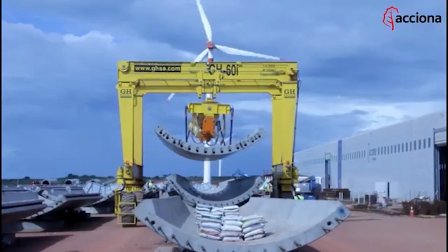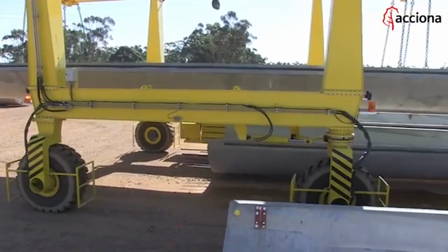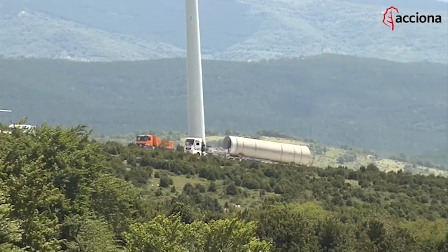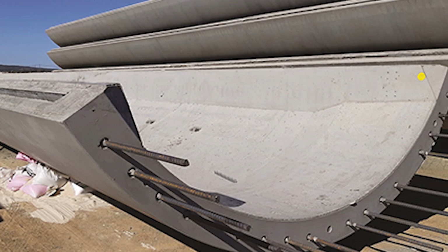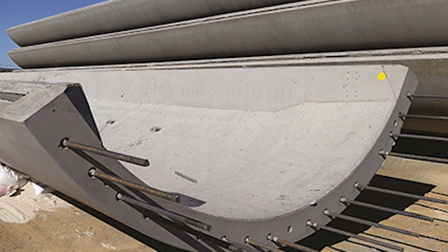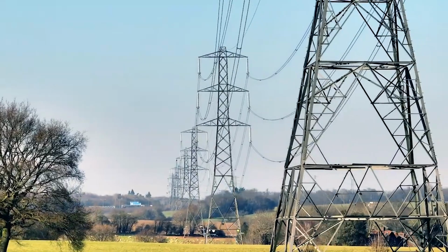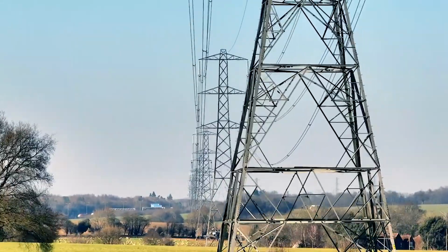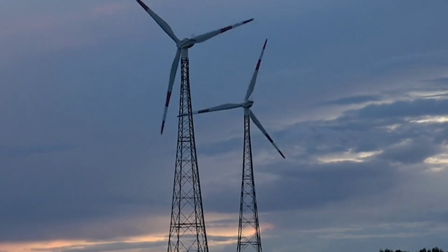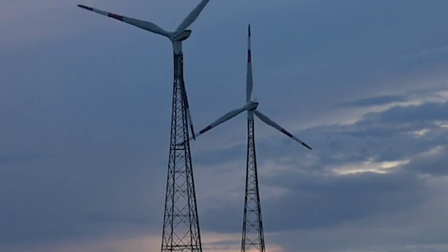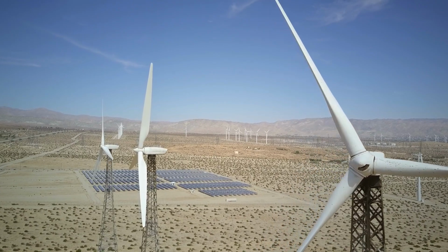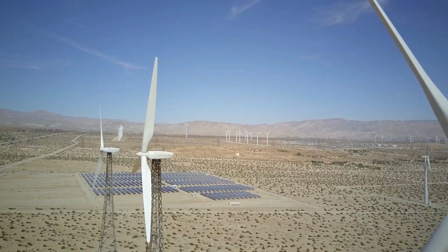Like the steel towers, the precast concrete towers are also manufactured in sections. All the sections are transported to the site and then assembled. These concrete structures have a large carrying capacity, allowing them to bear larger blades and nacelles. Finally, lattice towers are made from hundreds of steel materials, similar to traditional telecommunication towers. Since these towers are made in smaller steel sections, transportation is easier and cost is lower.